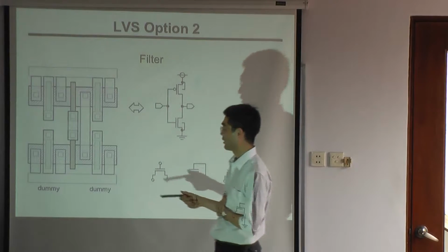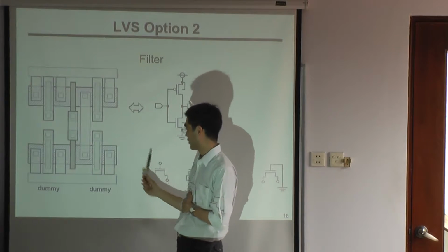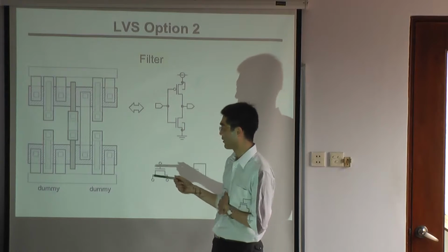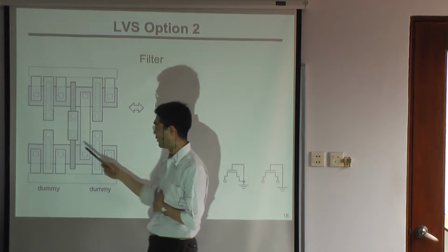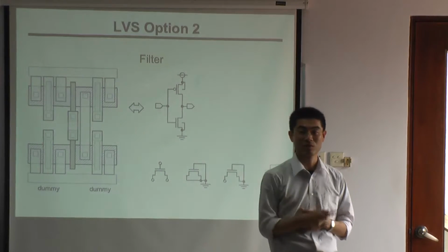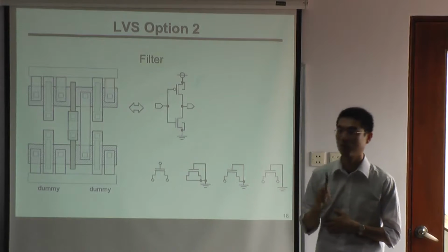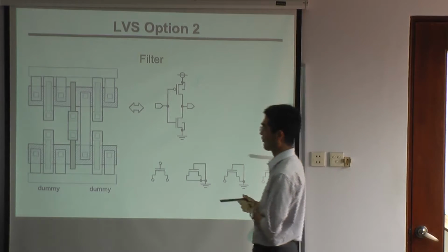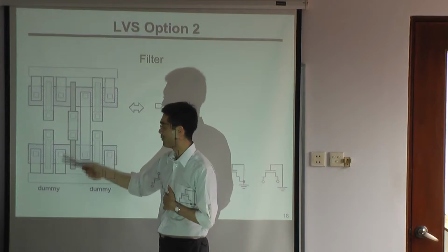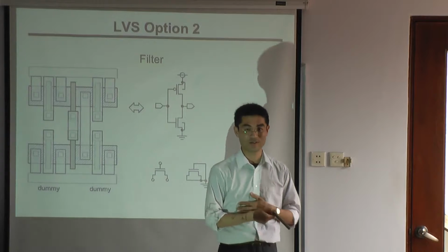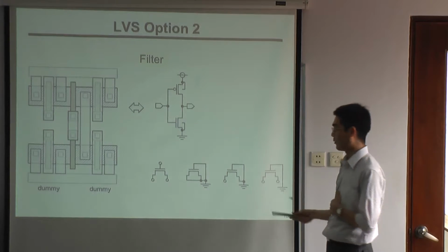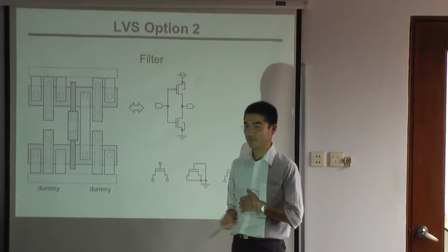Some technologies ask you to turn off all the transistors, and in some technologies, all the nodes should be ground. It depends on the technology and on your team. Actually, how to apply these dummy transistors depends on the technology, and your team has to decide what kind of filter to use.